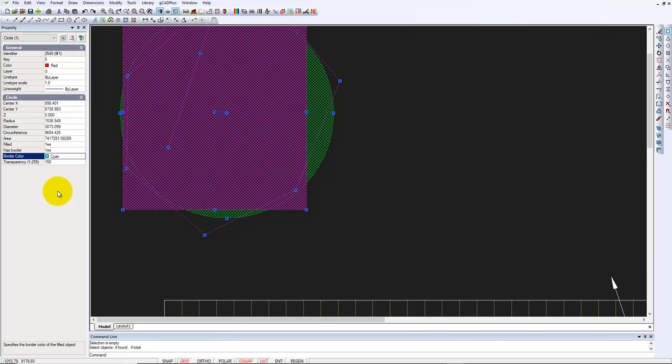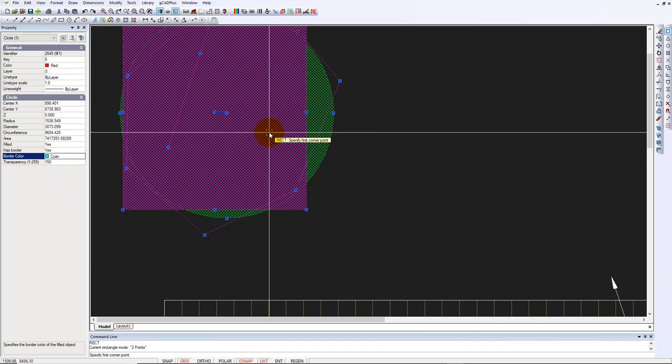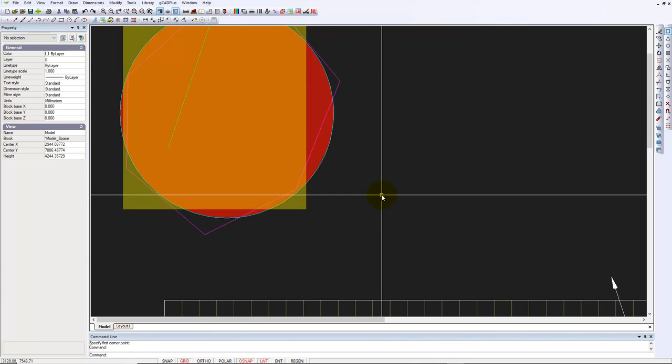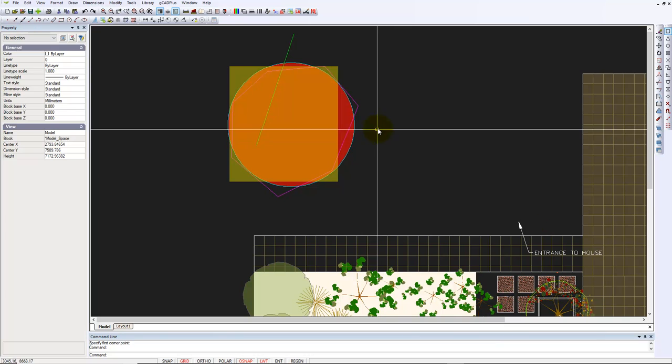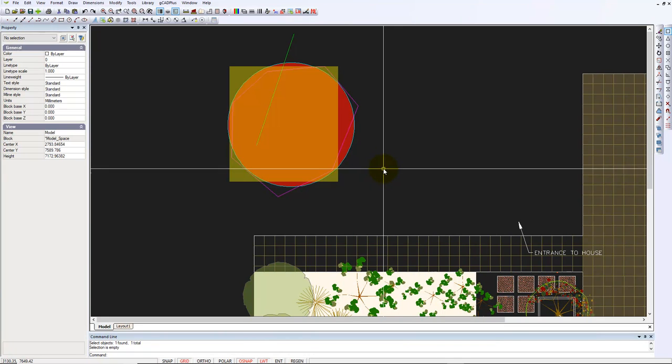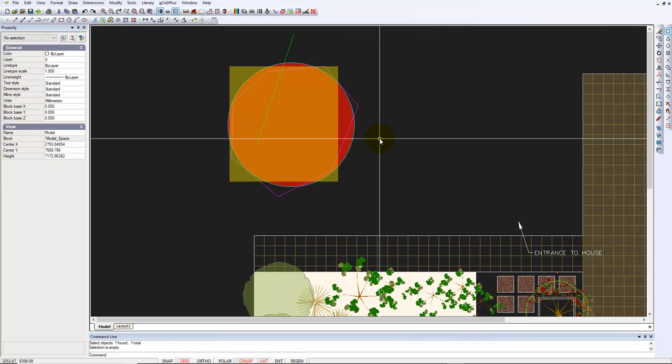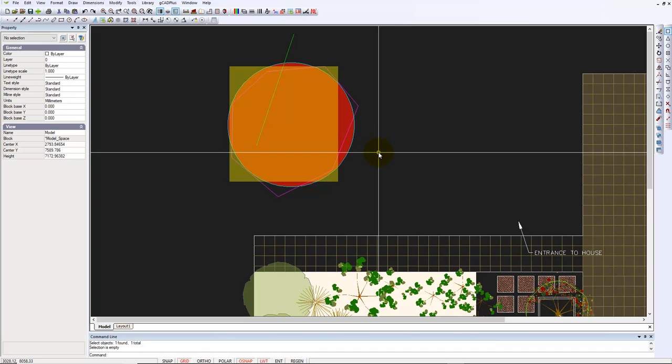So can you see I'm operating on the circle now, which has been highlighted green. So let's hit enter to burn that in, and right click, and we're done. So there's our colored circle that we just operated on. There's our filled rectangle. The other 2 elements we haven't played with yet. But I hope you can see that's very helpful, especially when entities overlay one another.